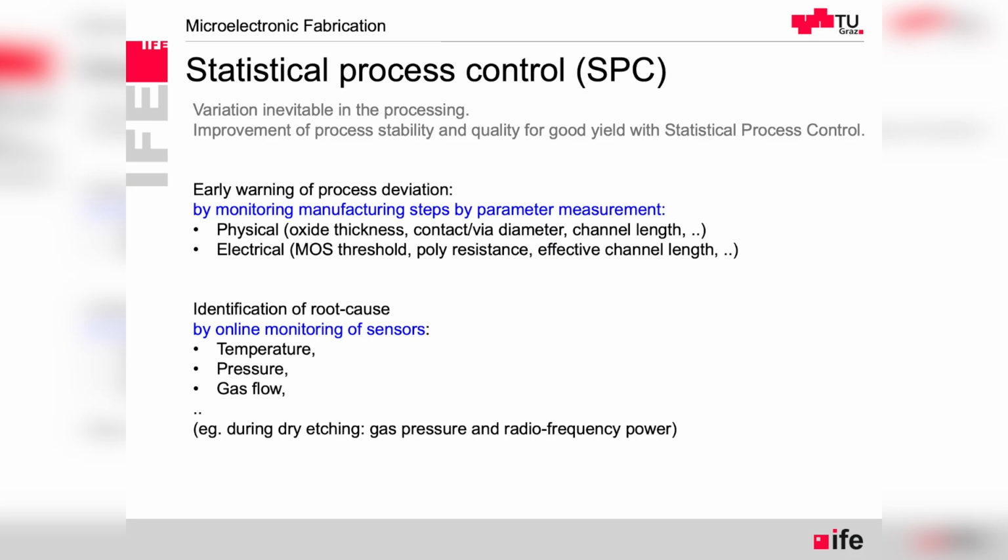And in terms of the control at the fabrication stage, there is something that we call statistical process control. Basically, it reduces to two parameters that I'm going to describe. It's about controlling each process step and describing it by a parameter so that we can monitor the stability of the process and, if necessary, improve it.